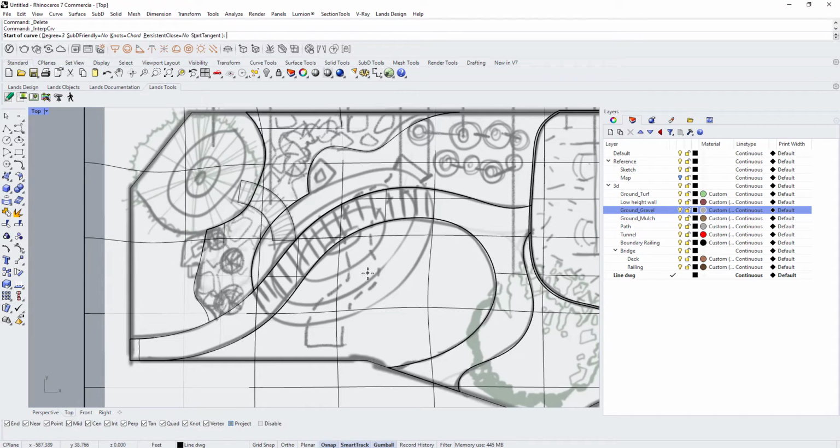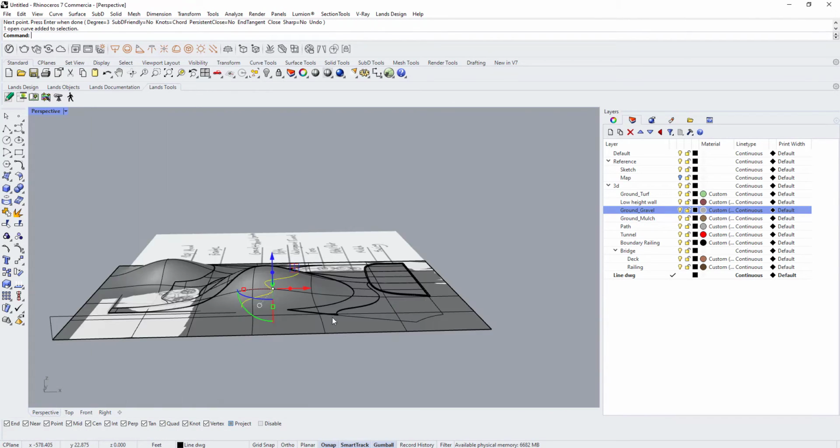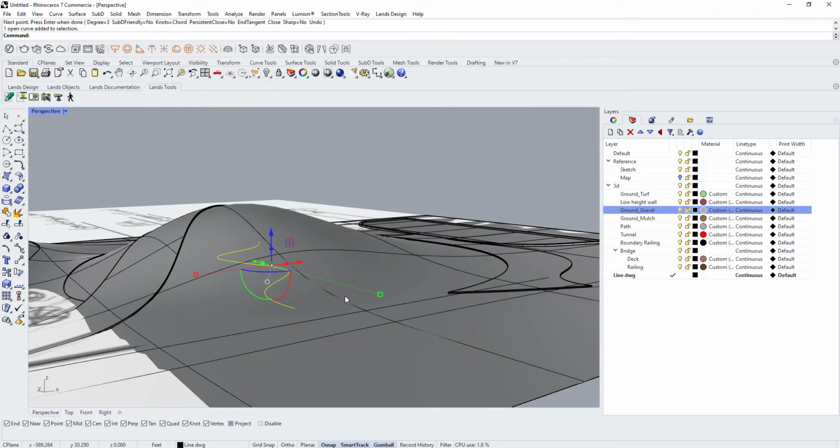That will create a 3D snap but in 2D planes. So all the curves I'll draw will be drawn in a flat plane, the XY plane. I will just draw the curve like this, and select that curve, go to perspective and type in pipe.